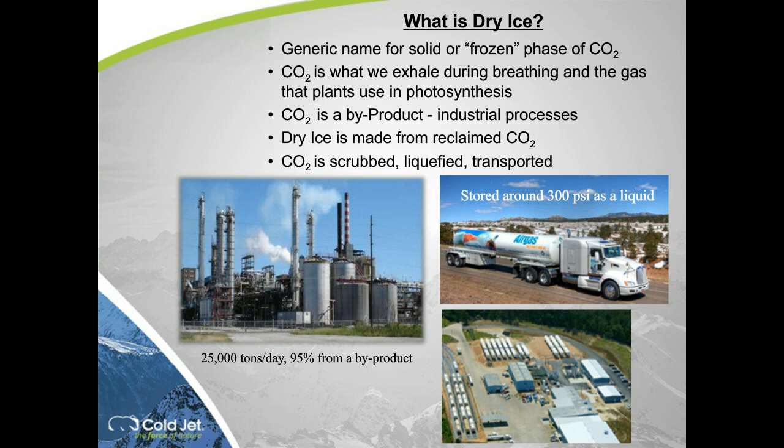A gas company will build a plant right next door to one of these manufacturing companies. They will reclaim that CO2. They will scrub it to get rid of whatever smell may be in it. They'll pressurize it, turn it into a liquid, about 300 psi. Then they can transport it to a plant where they can put it in a pelletizer and literally turn that liquid back into a solid CO2, and I'll show you a picture of that coming up.